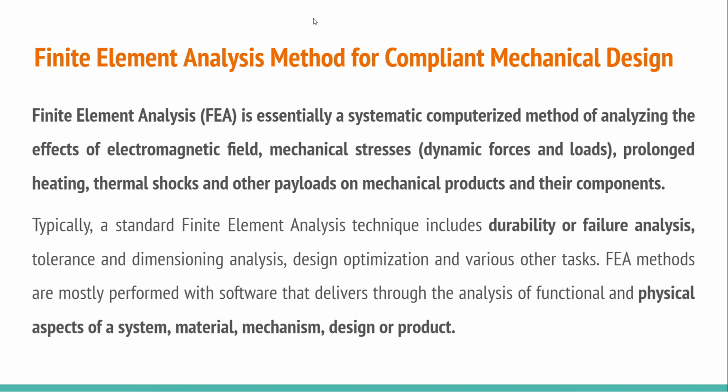So FEA is a numerical simulation method used to analyze how a component behaves under load, stresses, and boundary conditions. The model is divided into small finite elements connected by nodes. Applications: structural analysis to calculate stress and deformation, thermal analysis to calculate temperature distribution, vibration analysis and fatigue analysis. Example: checking the strength of an automotive suspension arm before manufacturing.